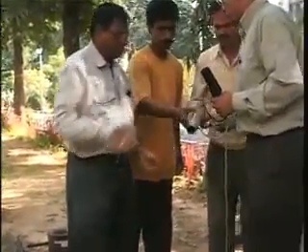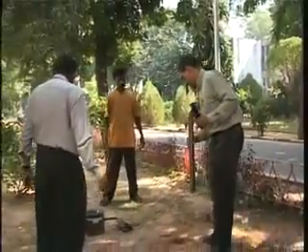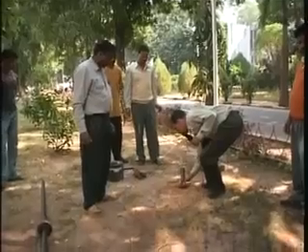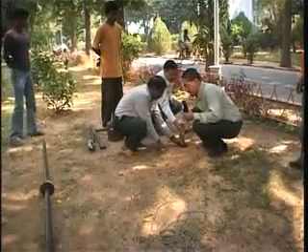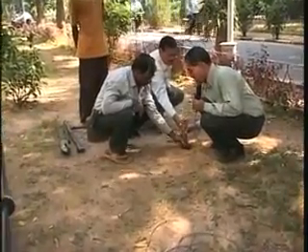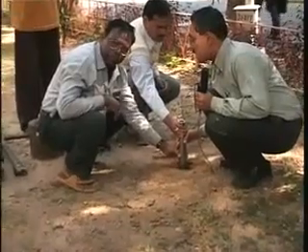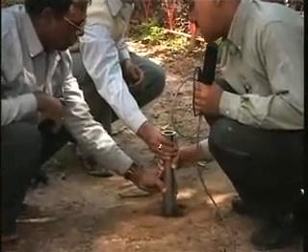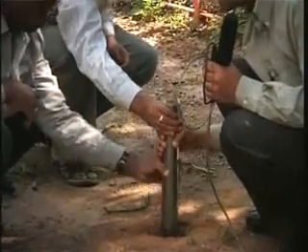And what we are going to do, we are going to drill a hole in the ground, and we just lower the sampler to the depth drilled, connect it to the SPT hammer with the standard rods, and drive the assembly with the standard SPT hammer, as you are going to see in the next little bit.